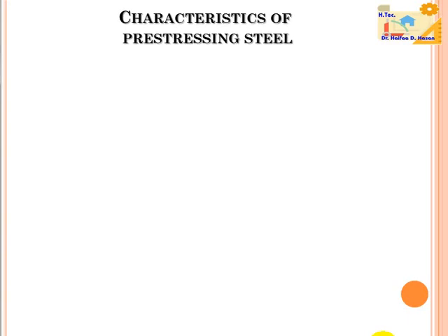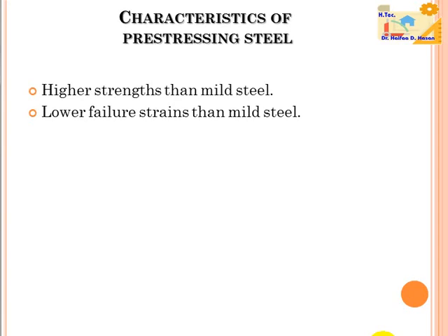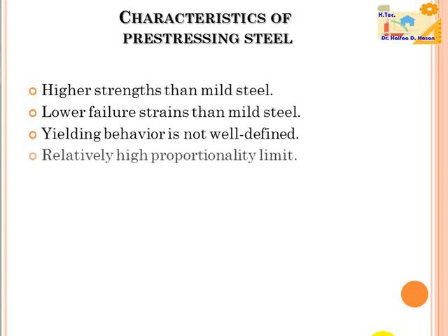Characteristics of prestressing steel: higher strength than mild steel, lower failure strain than mild steel, yielding behavior is not well defined, relatively high proportional limit. Thank you.